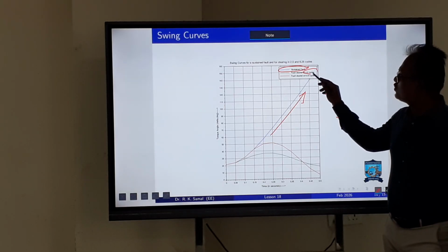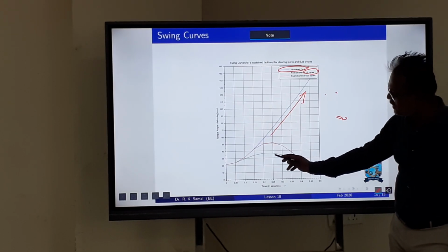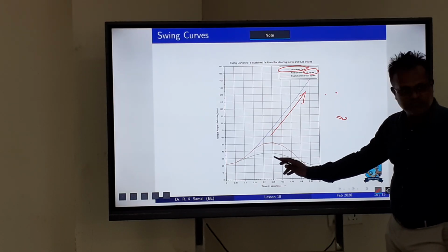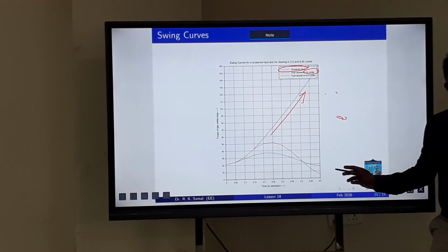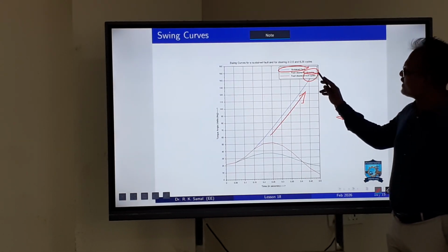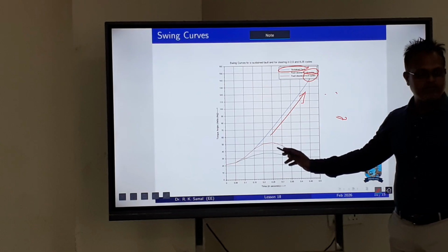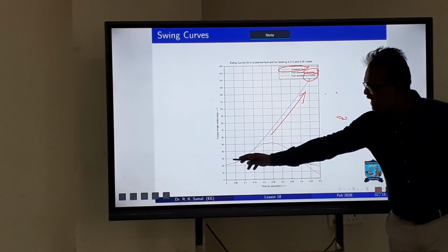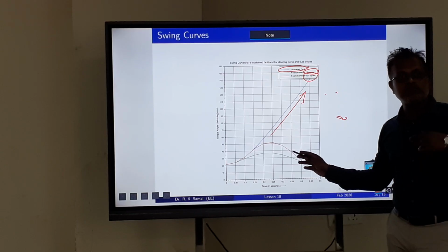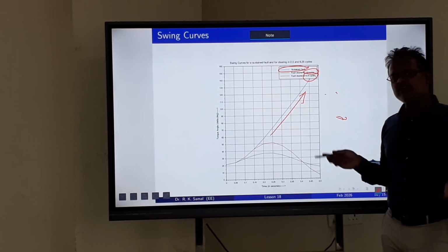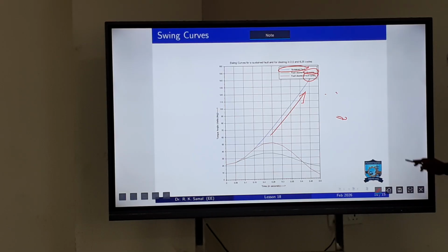When it is only 2.5 cycles, it is cleared. If you see, it's for the swing one. See, the deviation of delta is not much. Okay, it increases and then reduces. That means the system is stable. For 6.25 cycles, it is still stable, but the excursion of delta is higher. Torque angle delta in degrees is higher in that case. The fault is cleared at a higher delta. That means the critical clearing angle is much beyond that. Now we will see the results.